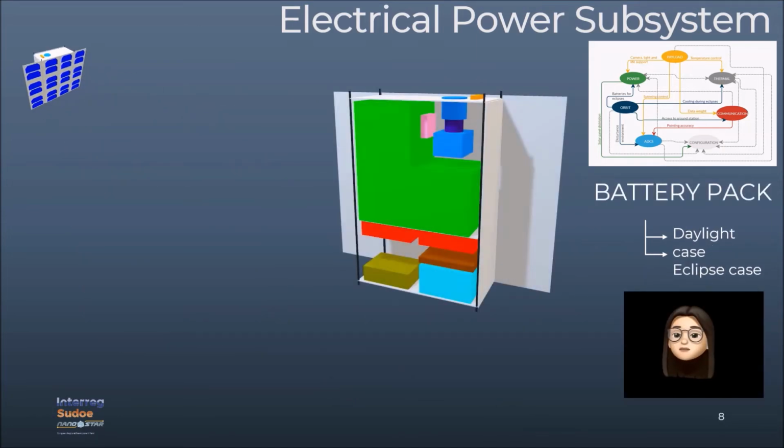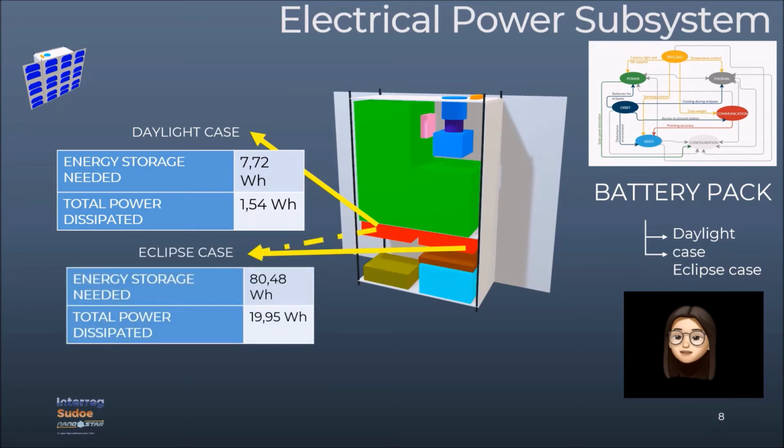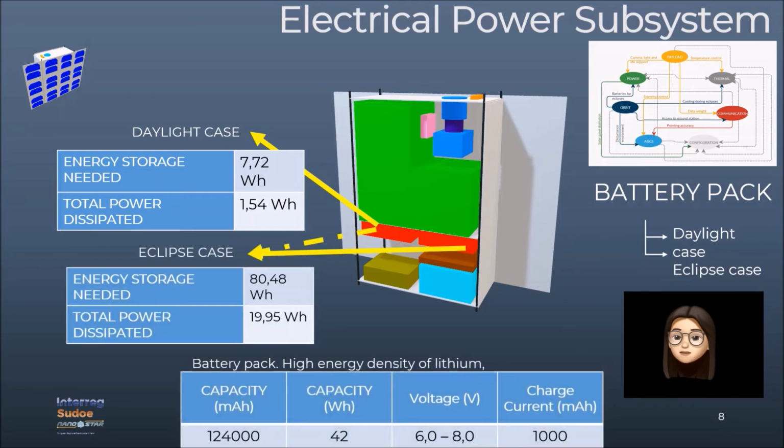The two batteries that this CubeSat design has offer the perfect solution for both the thermal and power subsystems. These are necessary for the peak power in the ideal case of a mission without eclipses, for full operation in case of eclipses, and finally offer the dissipation of extra energy to keep the temperature of the subsystems within their limits in the cold case of having eclipses in the orbital periods.